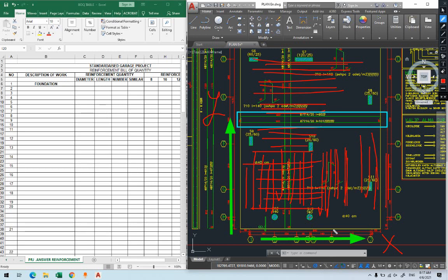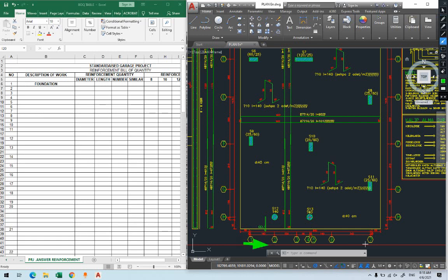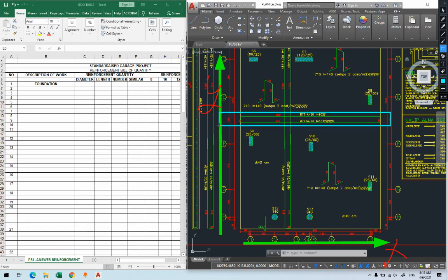So in order to make this one clear, we'll have two axes, x-axis, y-axis. Remember, this is x-axis, this is y-axis. For y-axis, you take the one that is perpendicular to y-axis, and for x-axis, the one perpendicular to x-axis. This is between me and you. We're going to use it when I'm asking you to calculate, for example, reinforcement in the x direction for the foundation. You know which one I mean. So perpendicular reinforcement to the axis, and we know the horizontal axis will be x-axis.